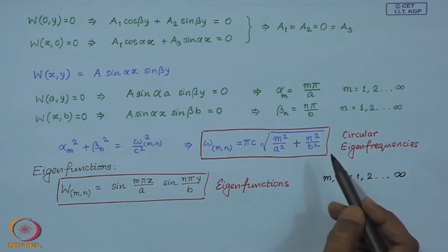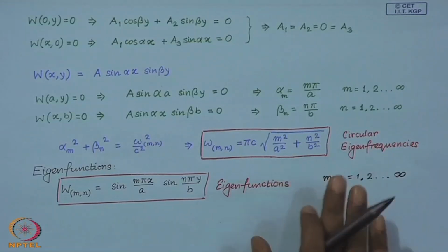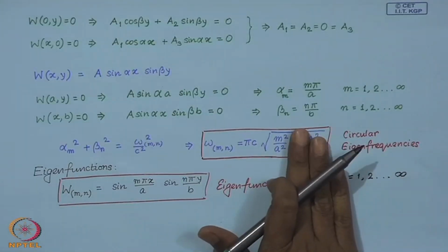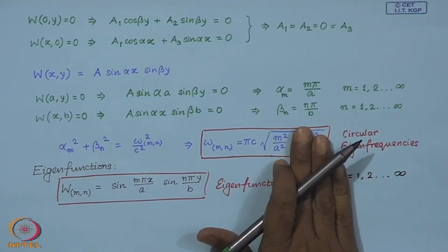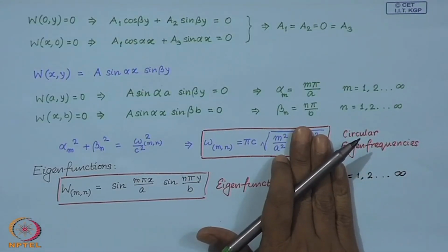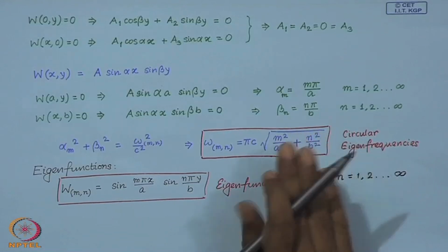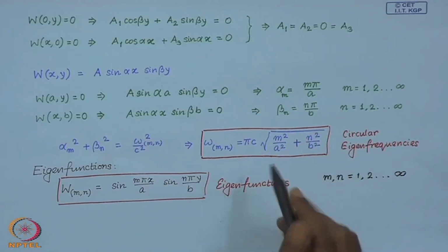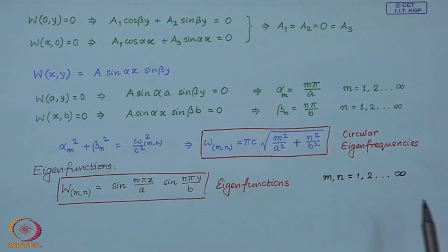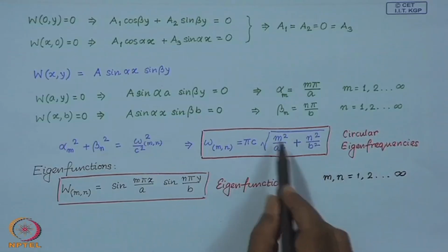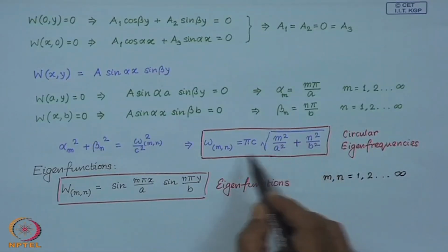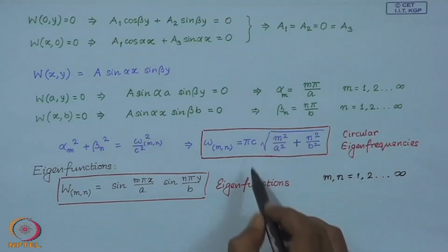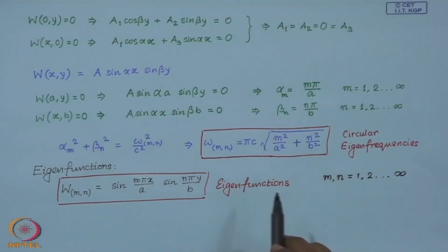what we have seen in strings. So, in the case of strings, suppose I simply block this, then you obtain actually the eigenfrequencies of the string. So, there you have seen that the higher eigenfrequencies are just integral multiples of the fundamental frequency. Now, in the case of the membrane, this is no longer true.